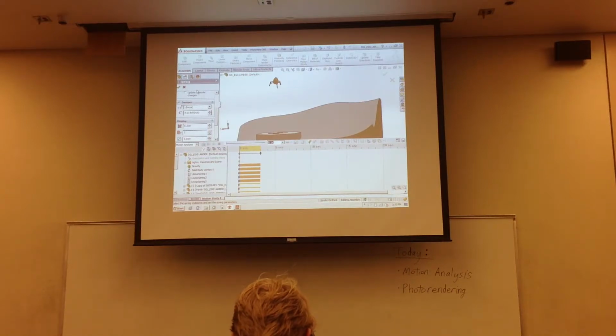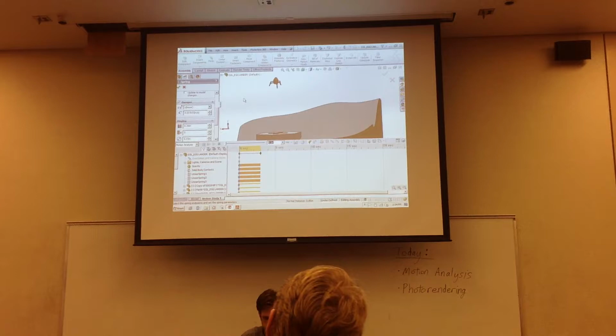Water is a really good fluid that mimics a damper. Like if you jump off the diving board and belly flop on the surface of a swimming pool, that hurts because you're going so fast it creates a lot of force. Whereas if you're walking through that same swimming pool at a slower rate, it doesn't create nearly as much force because the force is proportional to the velocity or the relative velocity between the objects.